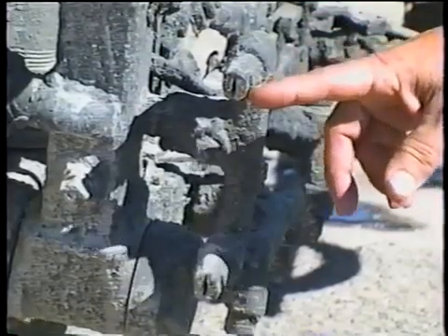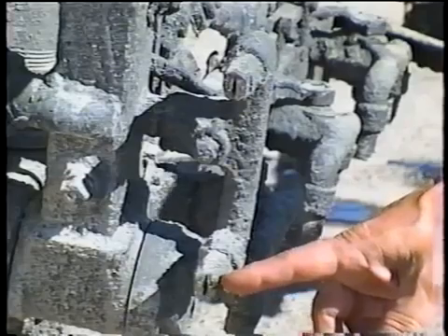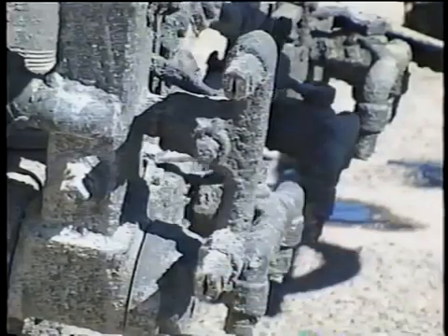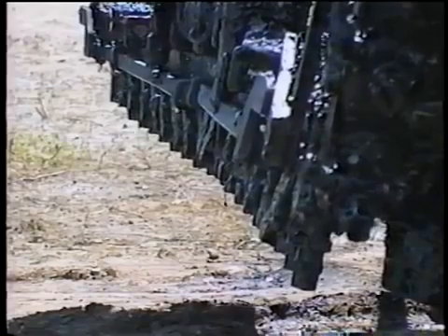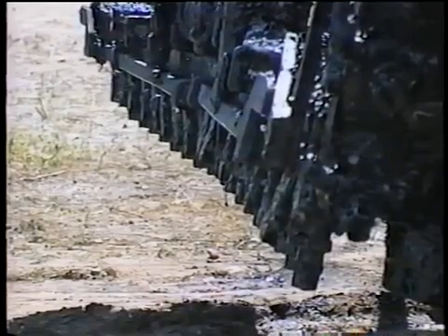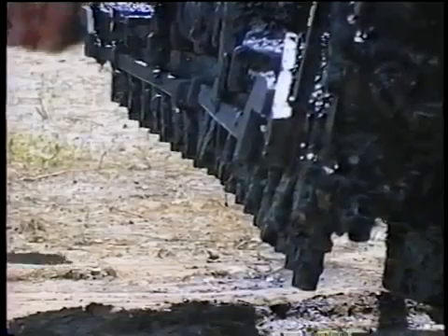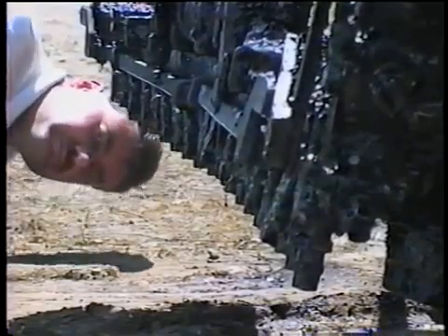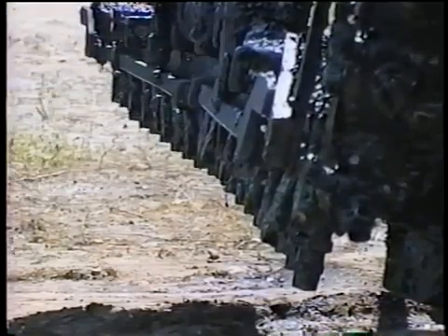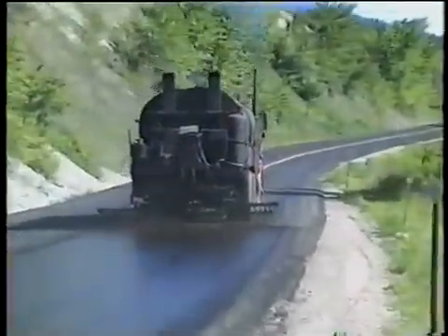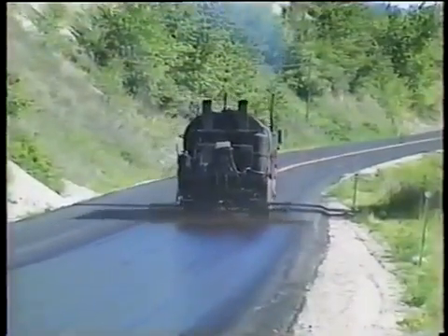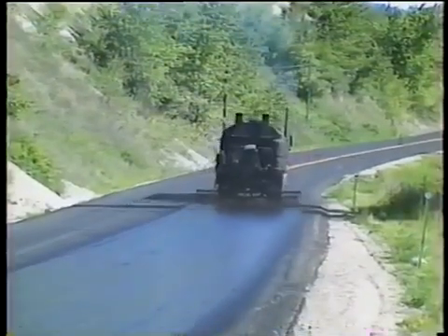Next, look at the spray bar, starting with the nozzles. They all have to be clean and angled in the same direction to get the proper coverage. And check the height of the spray bar. The proper bar height, nozzle angles, and application pressure determine the quality of the tack spray pattern. Generally, you want a double or triple lap coverage. This is a good tack application. Smooth, even, and uniform.